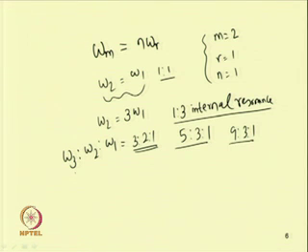When we have this integer relationship between the modes, due to the nonlinear terms present in the equation of motion, one can show that the higher modes are resonated when the system is excited at a frequency near the lower mode frequency. The higher modes are excited by the lower modes, or the lower modes by the higher modes, without any external force.